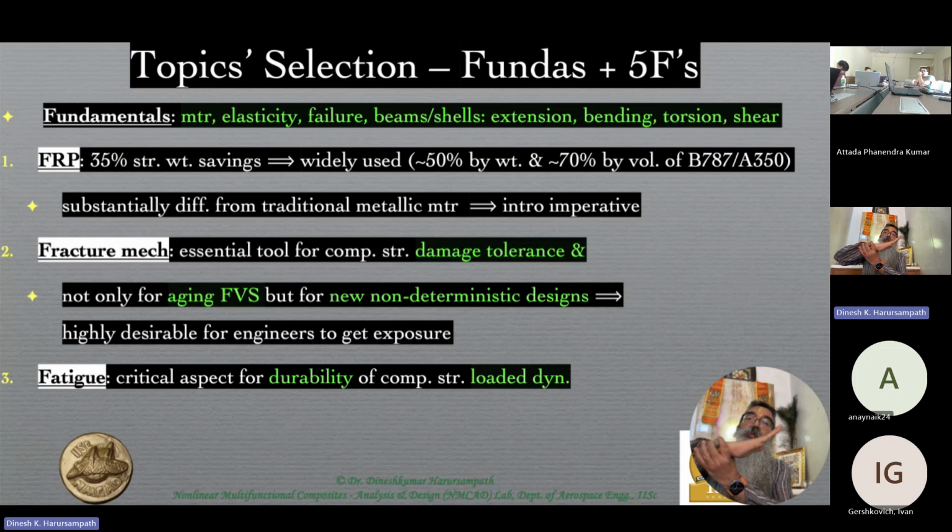And then when it's on the ground and not flying, just taxiing or doing whatever operations on the ground, it's just the self weight of the wing and therefore it will be bending downwards. So within a single cycle of takeoff to landing and going back to its hangar, the aircraft is going through a very large bending in the upward direction and a small bending in the downward direction. This cycle goes on through each of the flights, and it becomes even more severe in the case of fighter aircraft where certain maneuvers need to be done.